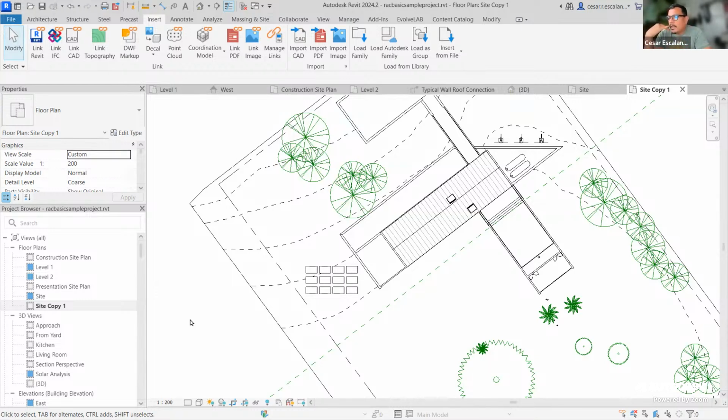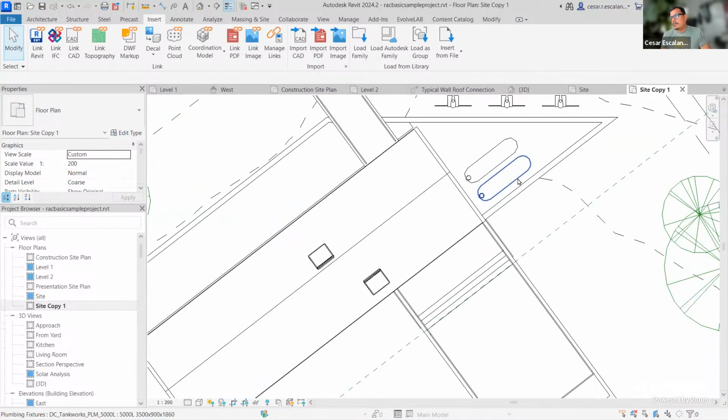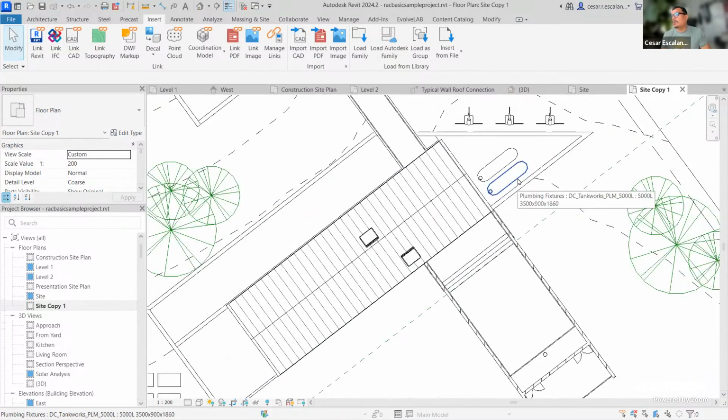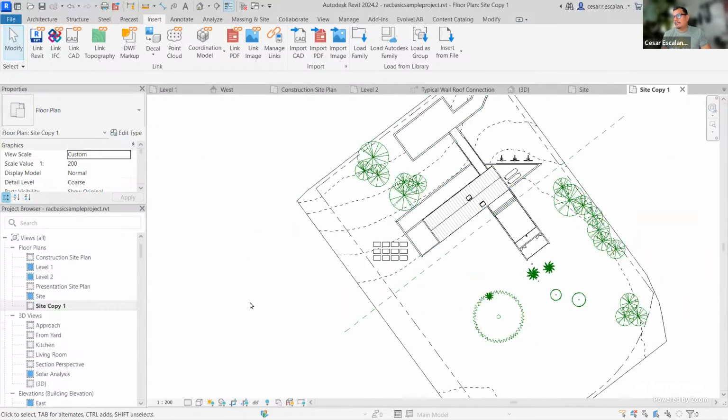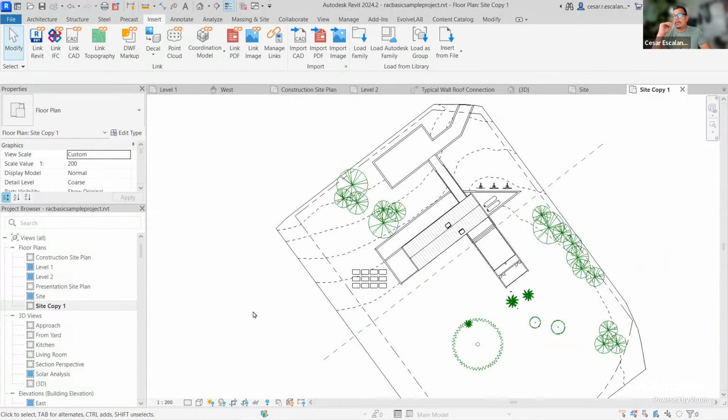To serve the purpose of this view, maybe the roof and the walls need to be grayed out. Or, for example, if you bring in the mechanical drawings, the mechanical link, that's information that's not relevant for landscape, but you want to show it as a reference, and you need to tone down your consultant's files. So I'm going to tone down the walls, the floors, and the roofs. And the fastest way to do that is by applying an override using visibility graphics.